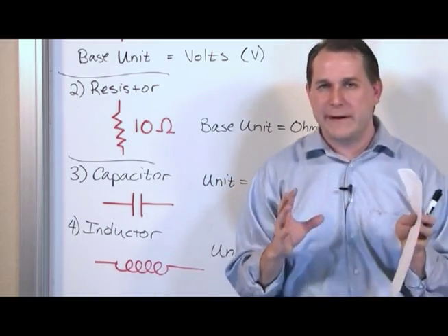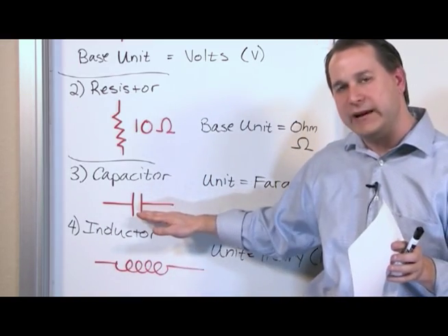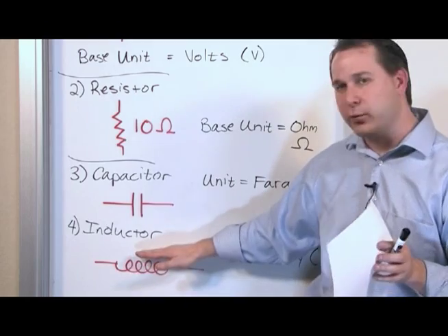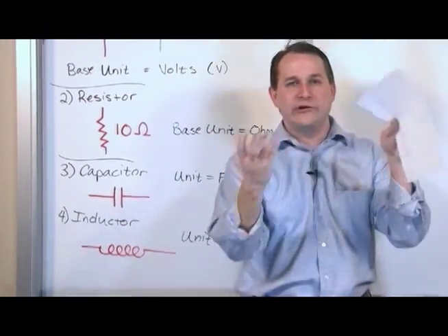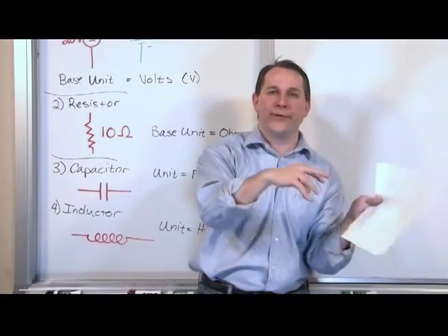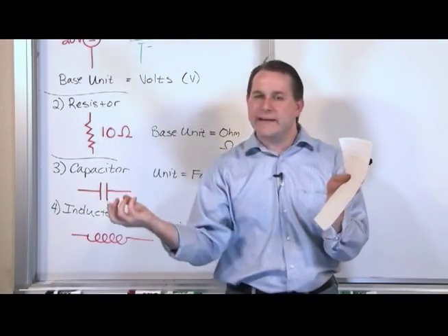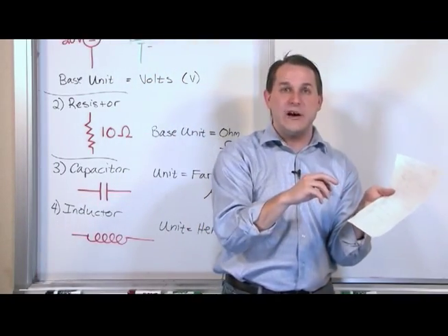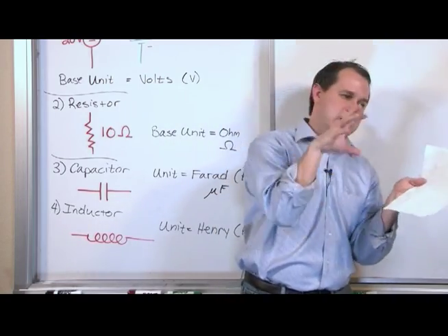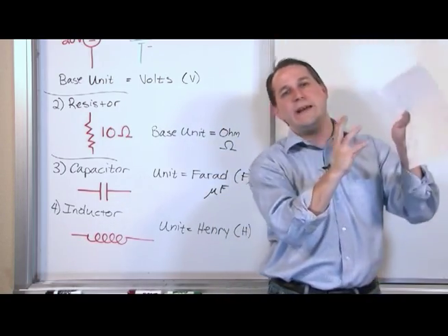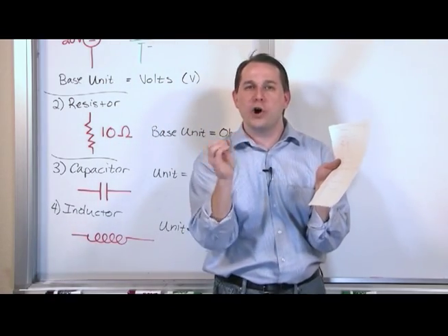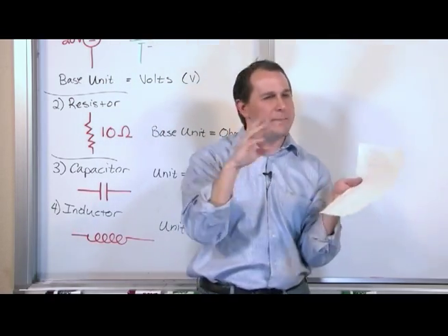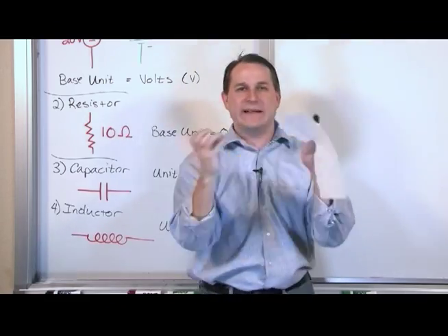showing a real circuit, but basically, since this guy stores energy in an electric field, and this guy stores energy as a magnetic field, when the wave comes in, you get this situation where they start sending energy back and forth to one another. The capacitor sends energy into the inductor, and the inductor kind of collects that energy. And then on the next cycle, it sends the energy back to the capacitor. And it goes back and forth in this perfect harmony. It's called resonance.